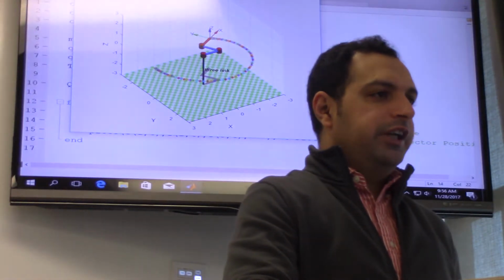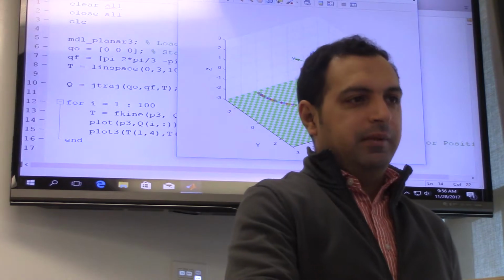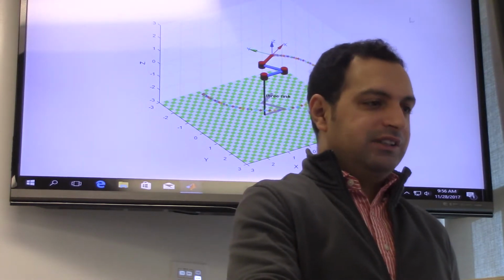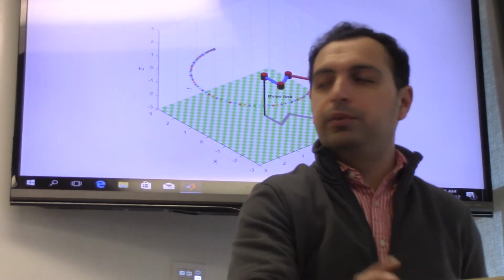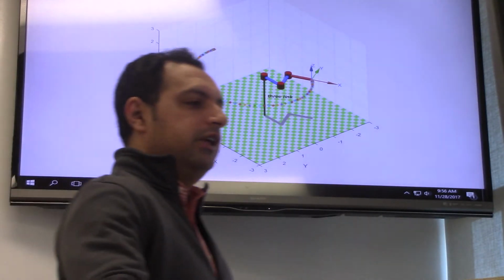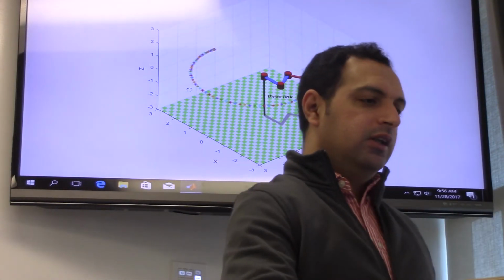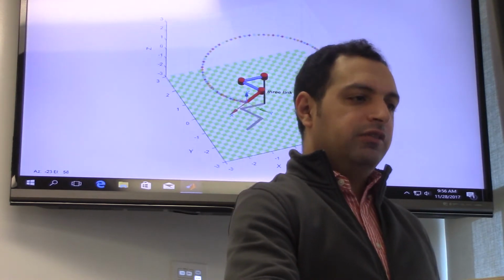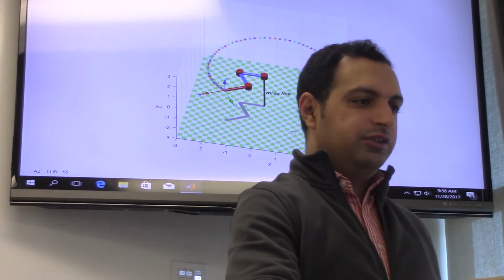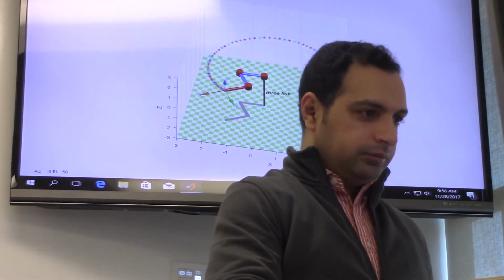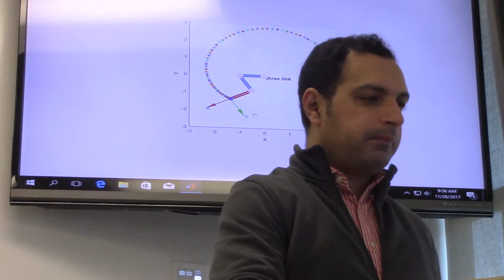Okay, so you can change the trajectory and you'll see, I mean, this is a very simplistic manipulator, but if you have a complex one, you can actually see how the trajectory works. This is not a cubic or a quintic trajectory. This is a linearly spaced, time-based trajectory. But for your own model that you generate, the previous ones that we did, cubic and quintic polynomial, the trajectory will not be as smooth as this. You will have a different curve. This is a very symmetric one. Okay.